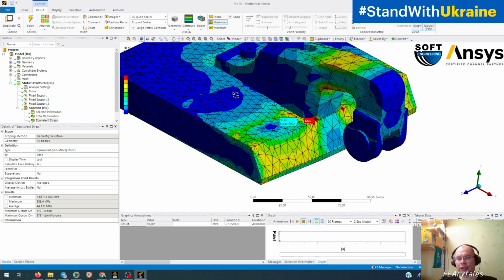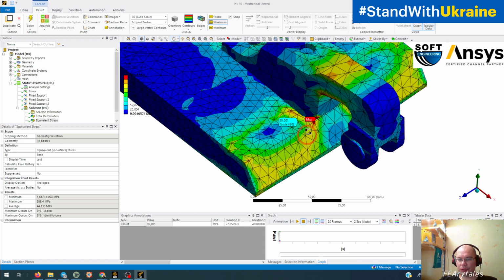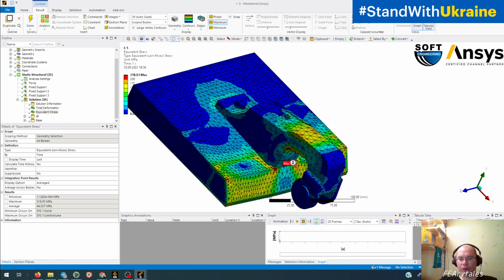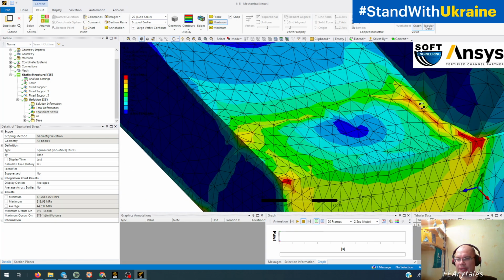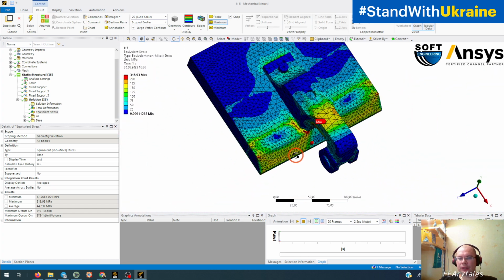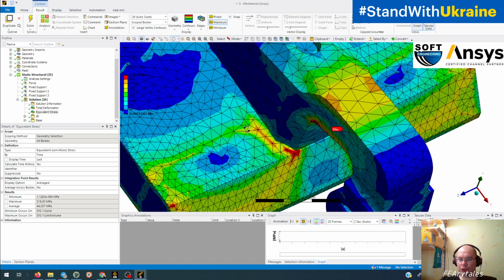If you want to analyze all places near the stress concentrator, you need to do a better mesh for obtaining something like that here in stress distribution. You don't need to improve the whole mesh for all your parts with uniform size. It can be done with different methods, but you need to improve your mesh in some places.